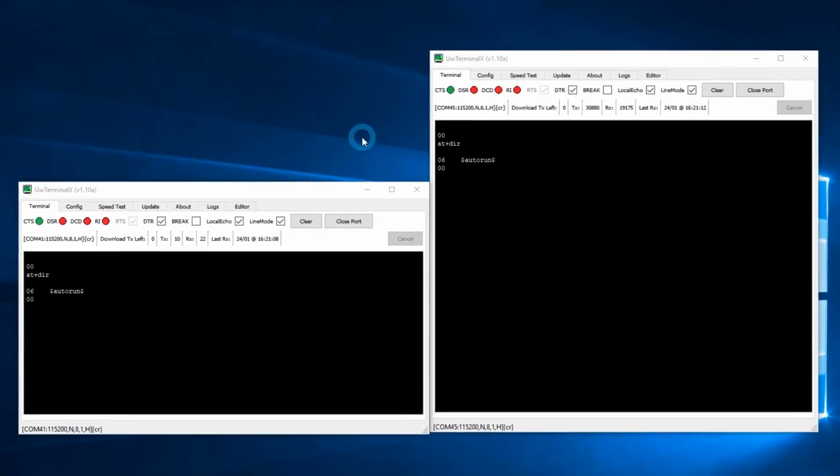Next, we will create and provision a mesh of up to 4 devices. We recommend 4, but only 2 are required. The devices get provisioned using nRF Mesh on either iOS or Android, which is developed by Nordic Semiconductor. Note that this video will only use iOS for provisioning, as at the time of recording the Android application is currently undergoing a refresh. Ensure all of your DVKs are connected to your PC with the power select switch set to DC 5 volts so that the board is powered off.